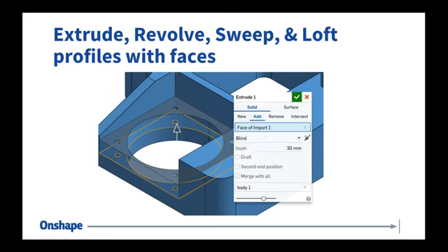Can you extrude at an angle? Sure, you can add draft. That'd be one way to do it. There are a number of ways you could create a pyramid, for instance. It's definitely a cool modeling example because you could build it so many ways. But if you're just trying to extrude at an angle, a draft sounds like the thing that you're looking for.